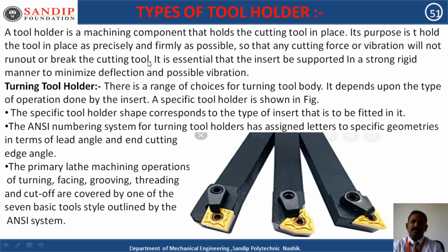It is essential that the insert, this golden color part, is called an insert. Under this, you have to fix the Allen key here, and this is the tool holder, again firmly fixed. That's why the insert must be supported in a strong, rigid manner to minimize the deflection and possible vibration.